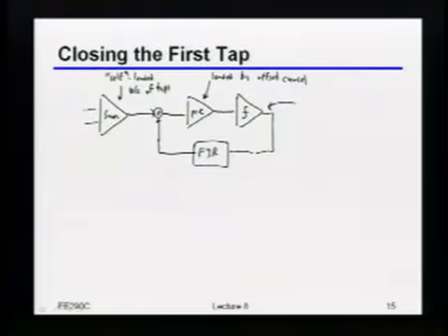Because if I do, then that implies that my transmitter has to be sending huge swings, and I'm just going to be spending lots and lots of power. Okay? So if I look at that comparator, there's going to be some minimum amount of time it takes me to just resolve the small input signal. And that minimum amount of time is going to be something like, let's say, whatever my input swing is, divided by 2. That's, of course, after the DFE.